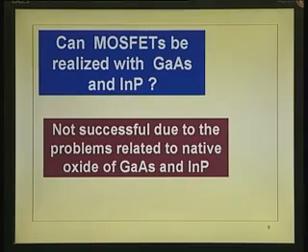Silicon SiO2 is native oxide. Whatever way you do it, it need not be thermal oxide. You just convert that silicon into silicon dioxide, that is native oxide. If you convert silicon into silicon nitride by thermal process, that is native nitride. If you deposit nitride, that is not native, that is just deposited nitride. Silicon dioxide also can be deposited by plasma enhanced chemical vapor deposition, by cracking silane and forcing it to react with oxygen, SiO2 you get, and that is deposited. That is not native. Native is true conversion.